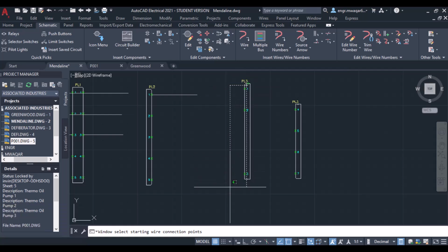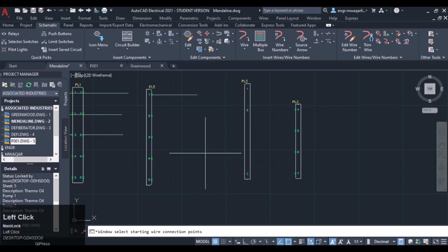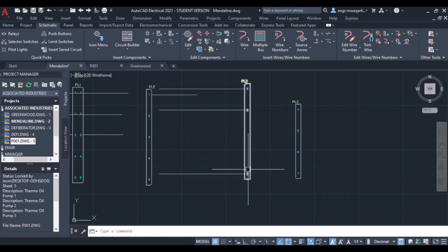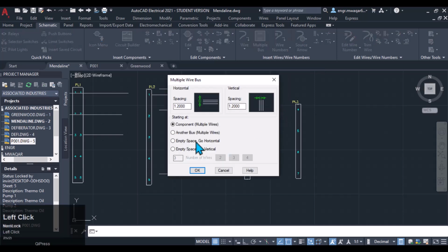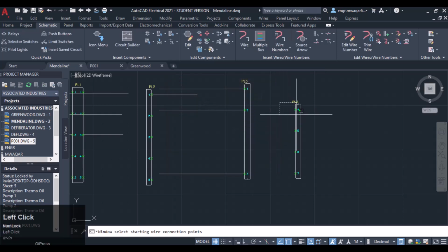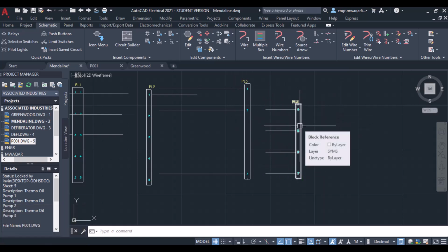Just like we have learned in how to connect multiple wires to a component, that's the same method. Just move your wires. You will see only these 3 pins are connected, so the space is left like we have added a spacer. Now if you want to enter wires to the other section, click here and move your wires. In this way we can add spacers and breaks between two connectors.